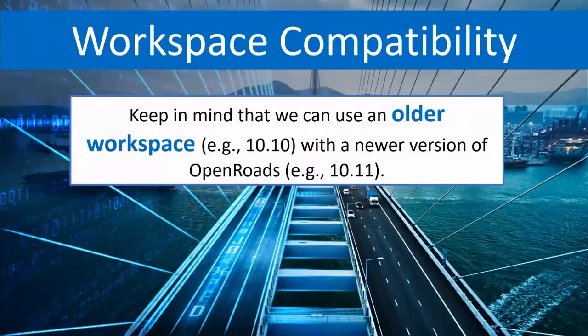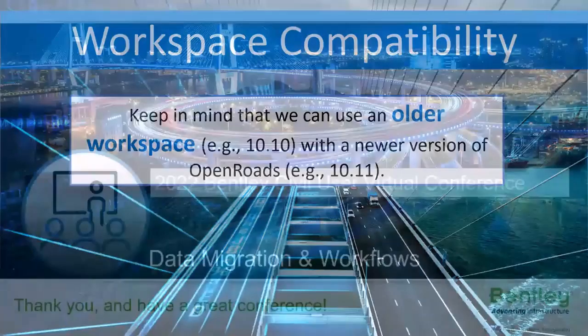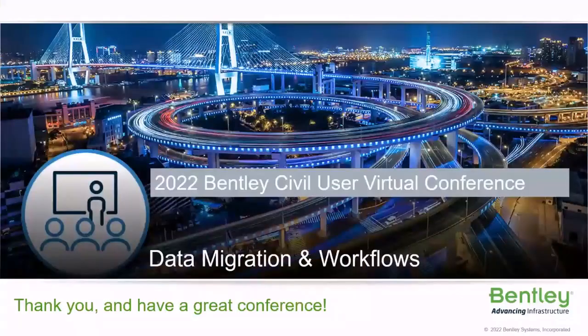Now, be careful, right? Because if you were to go over to that workspace and access, for example, a DGN Lib, it's going to say, hey, do you want to upgrade this? Yes or no? And so if you upgrade it, now it's a 10.11 file, right? So you got to be careful of that. But I did want to make sure everybody knows that older version workspaces are compatible with newer versions of OpenRoads. Well, that's all I've got.